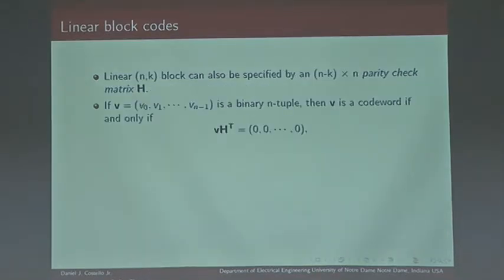The parity check matrix view of defining a code is more towards making it easier to decode, because checking parity is what you have to do to decode. So that's done from the parity check matrix. We'll see this in a minute. And low density parity check codes, for example, are defined from the parity check matrix.